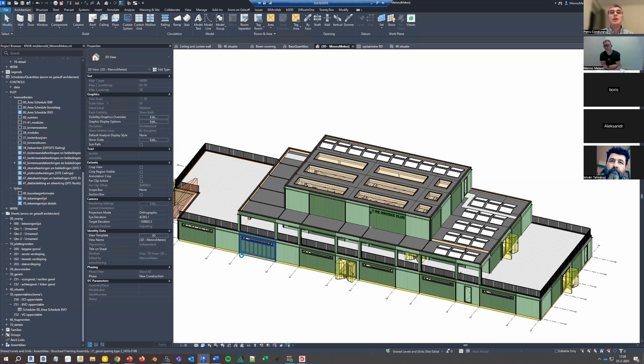So in order to leverage full support of the IFC schema, you have to use its elements. When we put everything into this pset, we decide to create another IFC schema inside the IFC schema, our own IFC schema, right? And that's fine, because the idea is for the IFC schema to be flexible. But be flexible after you are already using the basic things that it provides, okay?